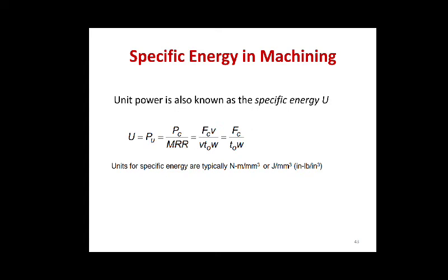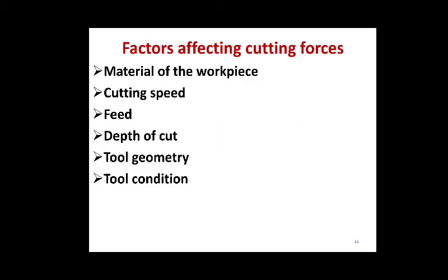Now let us see the factors affecting the cutting forces. First, material of the workpiece, cutting speed, feed, depth of cut, tool geometry, and tool conditions. These are the factors which affect the cutting forces.